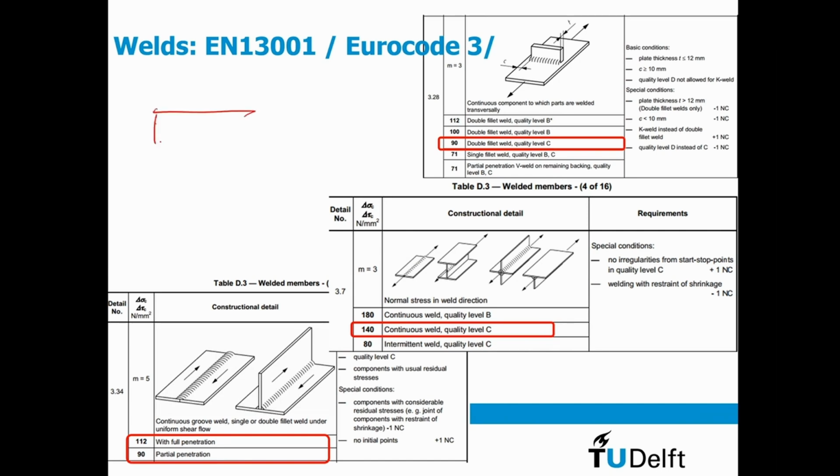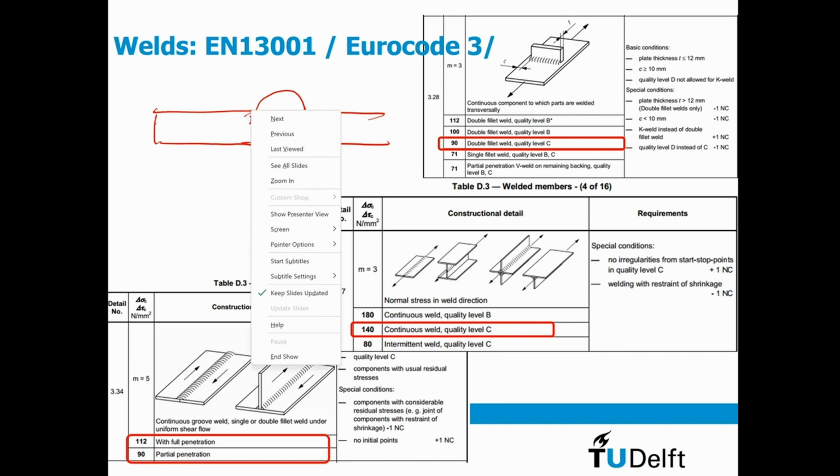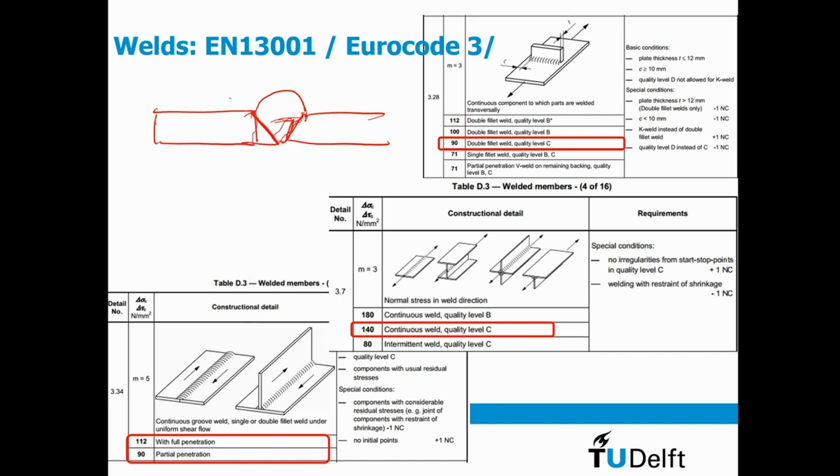If I have a weld, let's put it this way. I have a crack here, maybe initial crack, and if I make this in 3D, the crack direction is this direction. So the most vulnerable stress variation is perpendicular to my weld. And you can clearly see that in the difference between this situation here and this one over here.